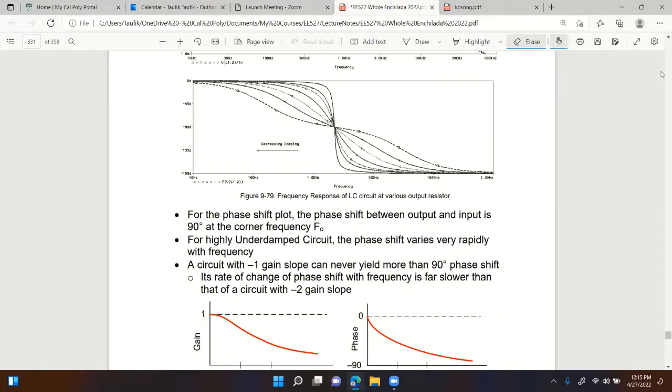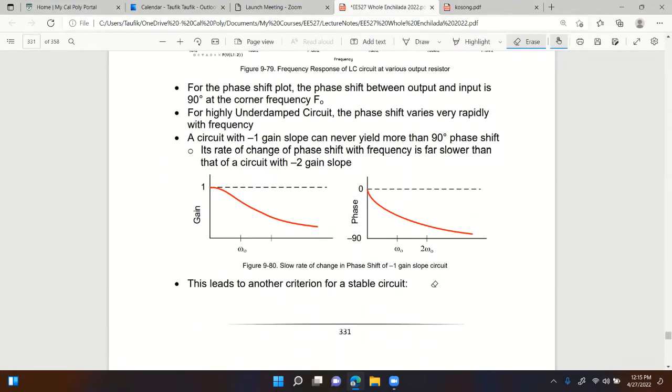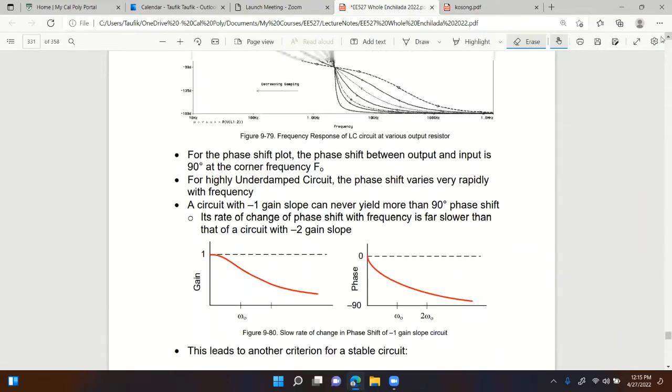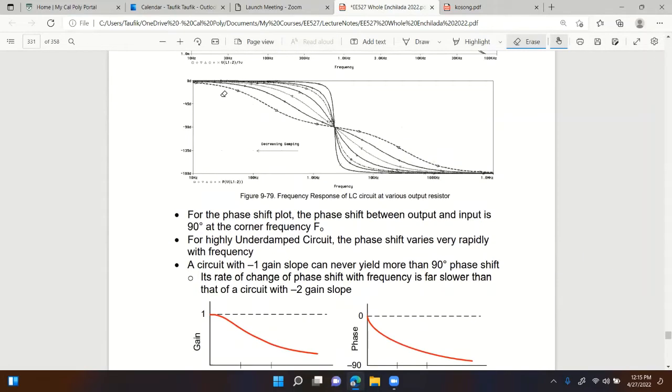the slope criteria, right? The -1 criteria, meaning at crossover frequency, it would be nice to have the slope at -1. Reason being, if the slope is at -1, then the fluctuation in the phase angles that would affect phase margin would be much less, such as this, right? You can see the drastic change if you have a slope -2.